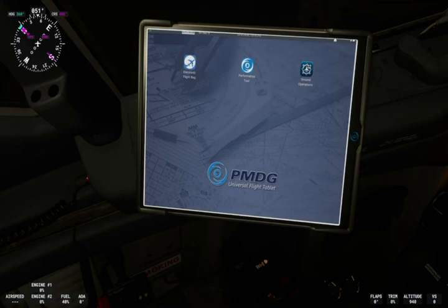We're running 2 amps because we've switched off ground power and we are now on, some would say, internal power. Right master caution off. Air systems master warning off. Left master caution off. Forward entry door closed. Transponder alt RPT off. Transponder TA only. Transponder TA RA. 1234.